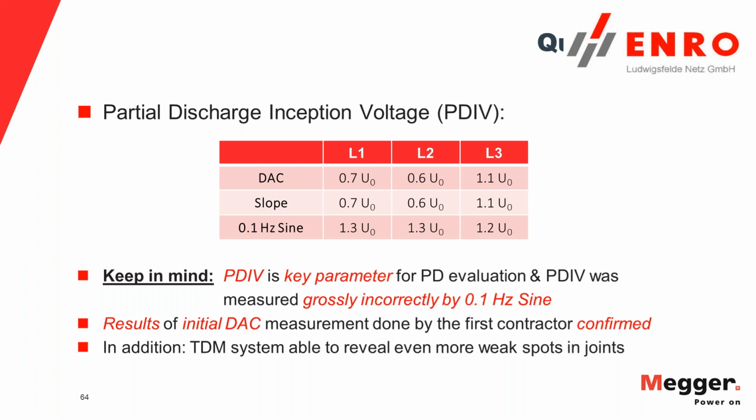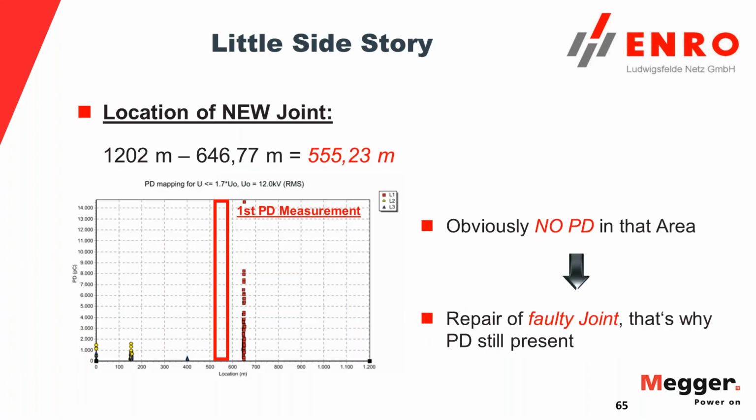You elevated it probably from green to yellow, so you monitor it closely, but you're not in an alarmed state. Like you don't say, oh, this is a critical condition. While the other two waveforms tell you there is failure imminent, and you have substantial problems in the splices.